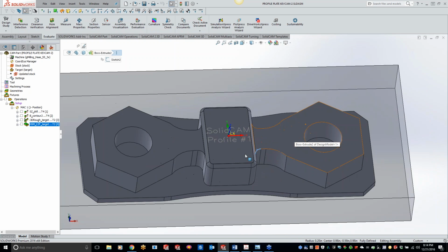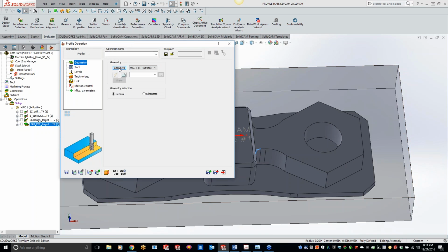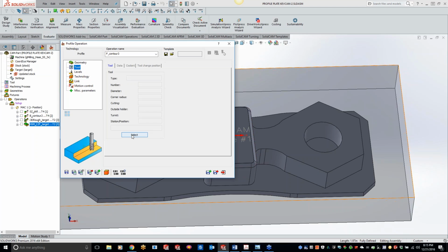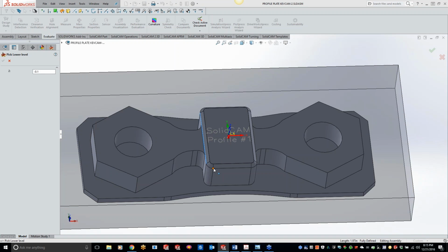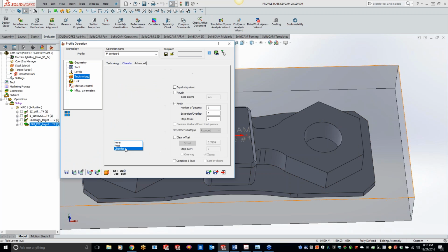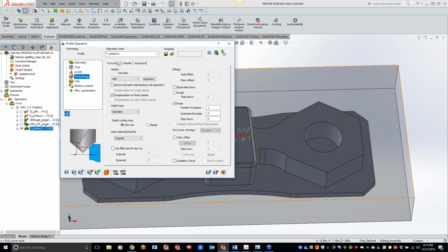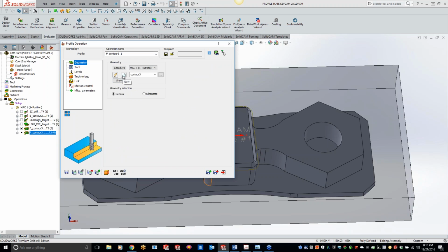Yep. Awesome. Okay. So we still have our chamfer. So let's go ahead and we'll just do a profile. And we'll go ahead and chain this guy here. Do our constant Z. Just use our spot drill that we have. Levels. Right there. And technology. I know this is a little bit of review here, but I just wanted to get it to look like the original part that we did a couple months ago. Now I'm just going to do a save and copy here, change my geometry,